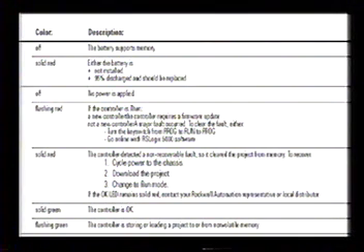So if the OK light's blinking at you, you need to load that firmware up. It might be a brand new controller, so you turn the key switch to program, to run, to program, go online with RSLogix software, and then you can actually download that.